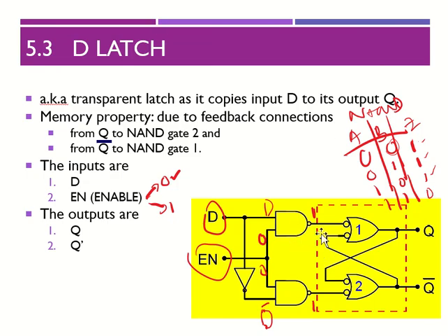So when your input is 1, 1 over here, the latch will cause you to have a hold situation in this output. Whenever you have an output of hold, this will hold when the enable is 0, so the Q will be holding its position.